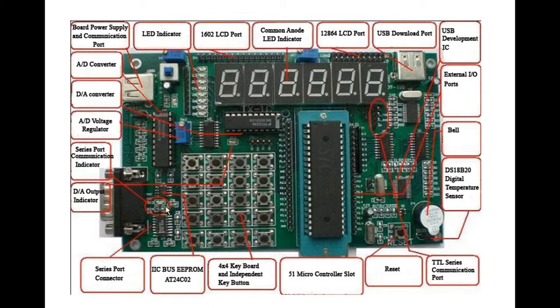Here, sorry, not this one. This one here is a very small chip, and this chip is the EEPROM, which has, I think, 256 bytes of memory. The reason why we need the EEPROM is that when we work on some experiments, we can have a piece of memory to record the variable status.